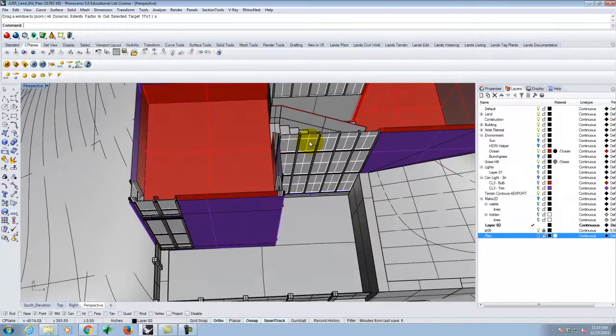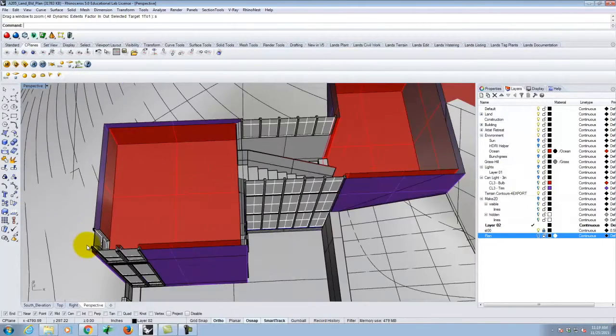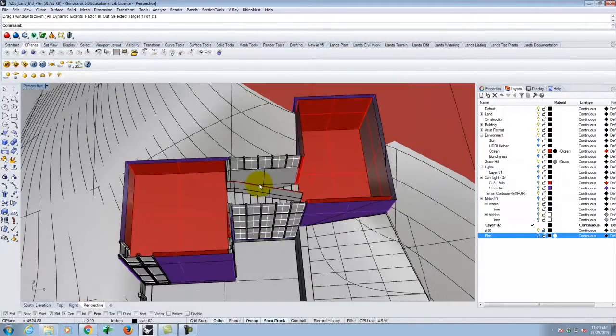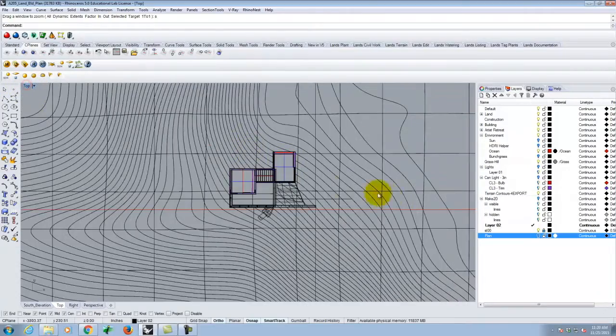Okay? It was supposed to fill in all of the walls, but it had difficulty with some of the walls, so I'm going to have to do a little bit of work afterward on that fill-in, like I did last time. But I have a pretty nice plan view. So now I need to start setting this up in a viewport so that I can export it. Let me jump into my top view, which is the closest to a plan view.